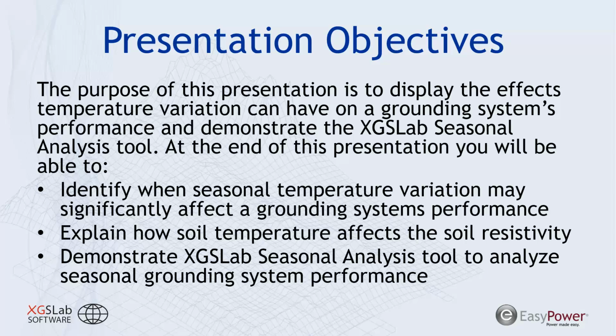So the purpose of this presentation today is to display the effects temperature variation can have on a grounding system's performance and demonstrate the XGSLab's seasonal analysis tool to help evaluate that seasonal variation. At the end of this presentation, it's my goal you'll be able to identify when seasonal temperature variation can significantly affect your grounding system's performance or a system that you're evaluating. I want you to be able to explain how soil temperature affects the soil resistivity. And my goal is that you would be able to use the XGSLab seasonal analysis tool by the end of this presentation.